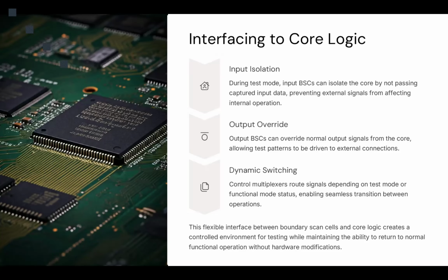Now, another aspect is dynamic switching. What's that about? When we want to switch between test and functional modes, this dynamic switching handles the control logic, usually using a TAP control signal, to control the transition between the testing mode and the normal or functional mode.